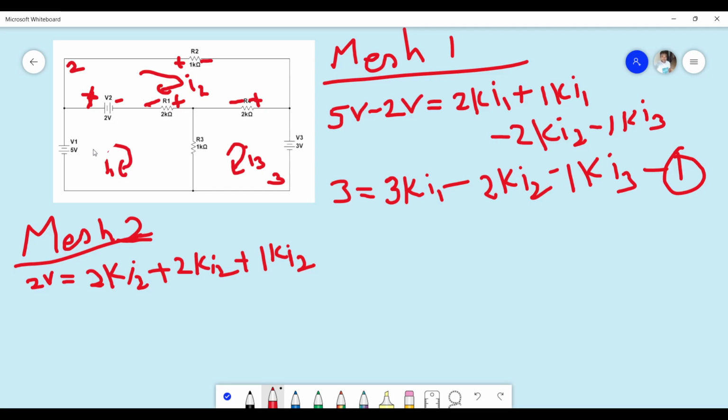So let us see the direction of mesh 1. The mesh 1 current is flowing through R1 in the opposite direction corresponding to mesh 2. This is flowing from negative to positive and therefore it is considered as a potential raise. But we are writing it on the potential drop direction. So we will write it as minus 2k I1. Similarly, the current direction of I3 is from negative to positive of R4. So we can write it as minus 2k